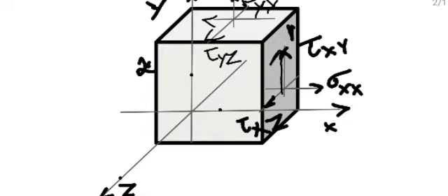Or this can be the other way too. Then on this plane and this plane, the shear stresses should be opposite to that. Anyway, that should be neutralized. So this one, tau, is acting in a plane whose normal is y, and it is acting in direction x. So it is tau yx.